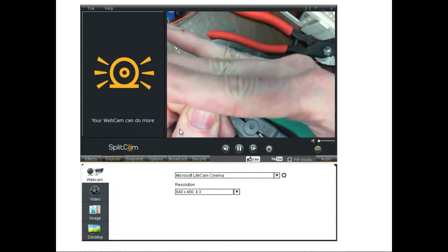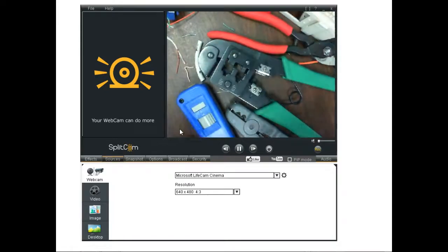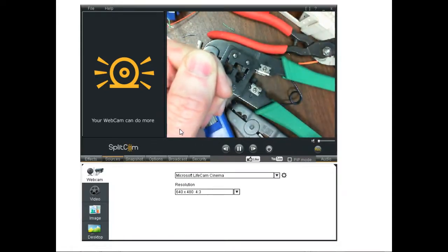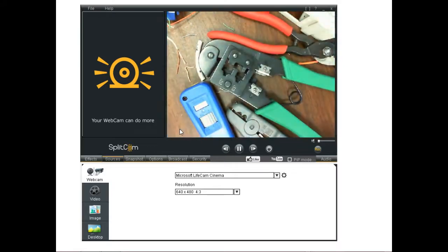I come up here and cut it, and then I take it instantly and stick it into the connector. And then once you get into the connector, guys, you got to do what? You got to let go because you got to push it in there. And you'll see that it's pretty flat, and it's real hard for if you got them in the right order for them to get out of the wrong order once you get it into the back of the connector.